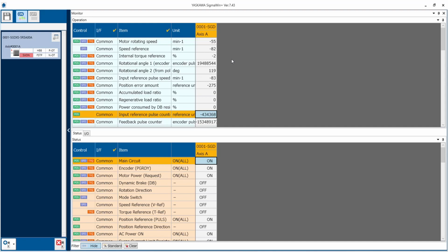Okay, now I try to shift the mode from position to torque. So the motor has stopped. So now I'll try to give the torque reference. So once I give the torque reference, the motor will run at minimum 200 rpm, whatever we have set. So make sure that you are limiting the torque. Once you input the torque only, your torque mode will work.